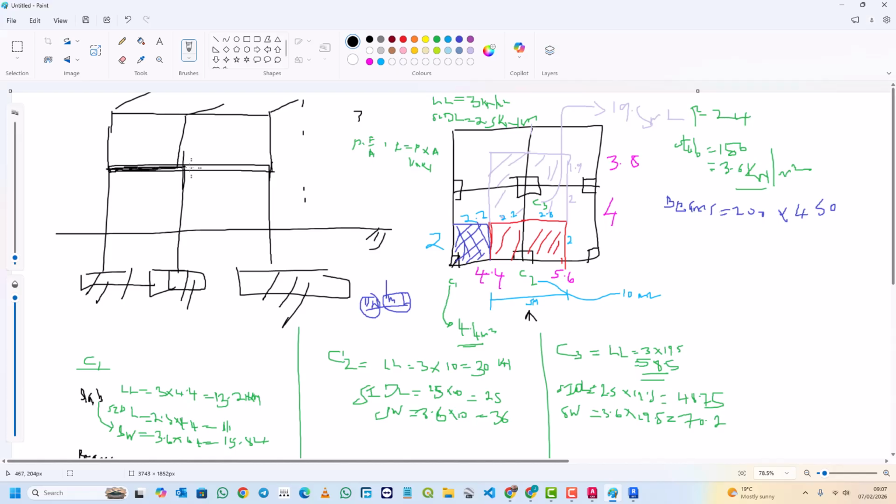right now we will keep the columns as line elements, because we don't know the thickness of the columns. We'll just keep them as lines. So this one is the slab, 150 millimeter thickness. Now when it comes to beams, it is 450. This 450 is from the top here to where it is ending, up to somewhere here. So this is the total thickness of the beam.